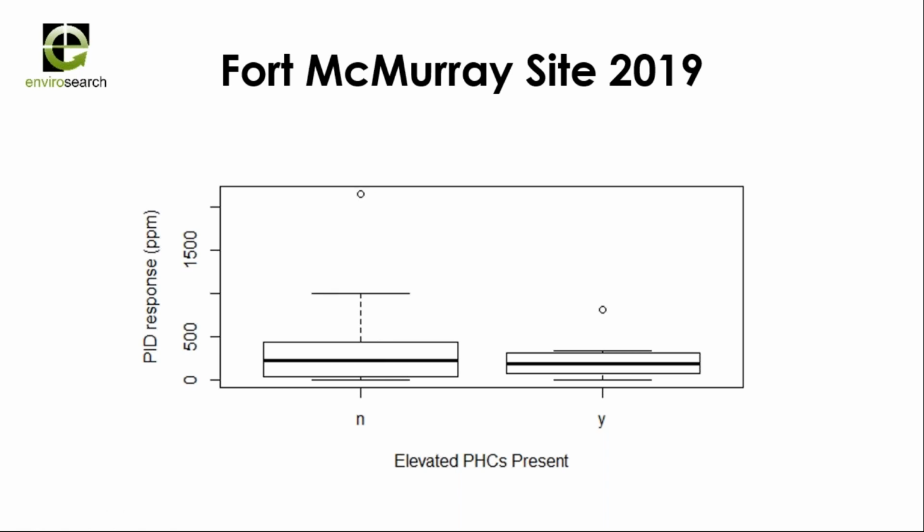So on this site that had weathered diesel, we actually found where we were getting a PID response, unlike the samples at Siksika where we were not getting a PID response for any sample. What this data is showing us is that there is no real relationship on this diesel site between the PID response and whether there was contamination present.